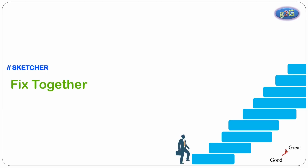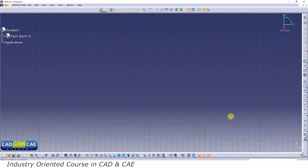Now let's learn about the next feature, Fix Together. Fix Together feature can be located on right vertical toolbar. Here you can see the tool fix together. It looks just like a paper pen. Now this is a feature which is used to fix a line, points, circle, arc or a geometry so that they do not change when other geometrical entities are modified. So let's try to understand in detail with an example. Let's create a geometry.